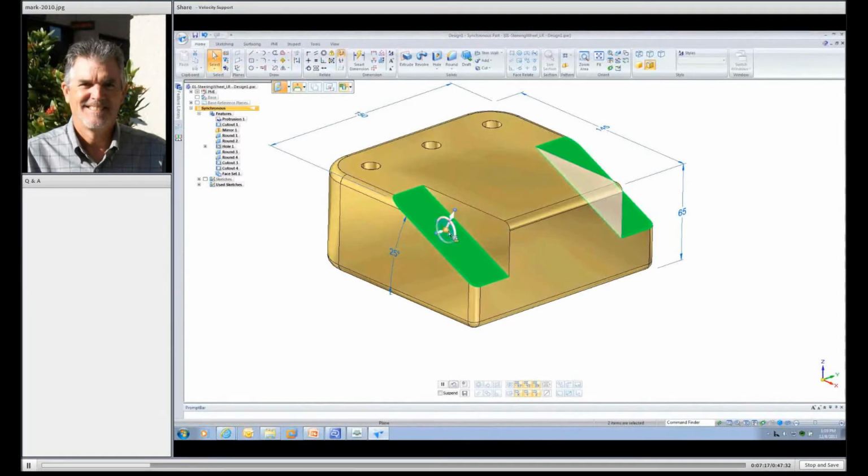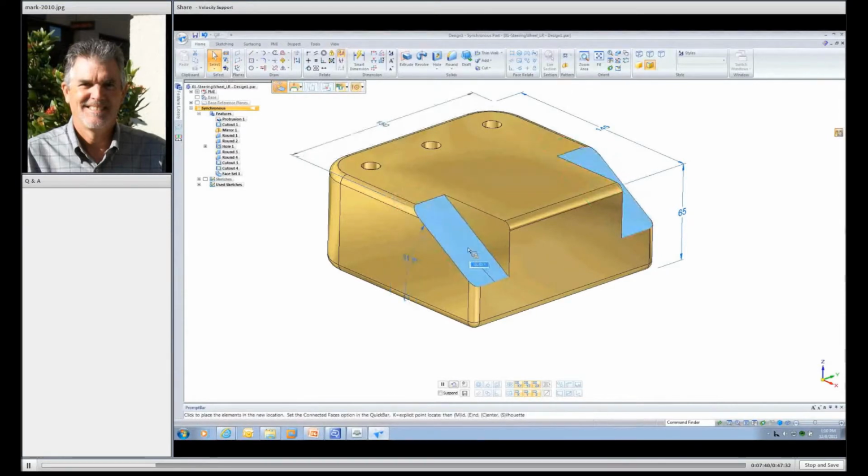So if I want to make a precision rotation, all I have to do is select the torus, if you will, and then it puts me in a rotate mode. So now I'm rotating this particular angle at a specific angle. Now obviously I could have selected the angle dimension and changed that angle, or in this case I'm just showing you how I can do it with the steering wheel. So let's just say I set this to 3 millimeters. Now the other neat thing is that if I want to change it from the opposite end, just drag the steering wheel up to that end, and then again click on the torus and change the angle from the top.